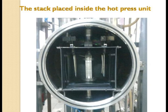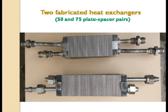Now you can see the stack, whatever I have made, is placed here. After that we will close the door. Then it will be pumped for vacuum, and after vacuum is reached, we will switch on the heaters. Supply power to these heaters, and you heat it up to the temperature of 150, and after 1 hour... it is a whole day affair to get one heat exchanger. One whole day has to be spent to get the entire process done.